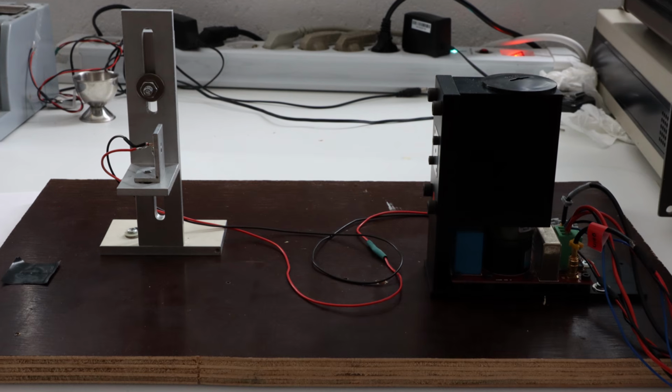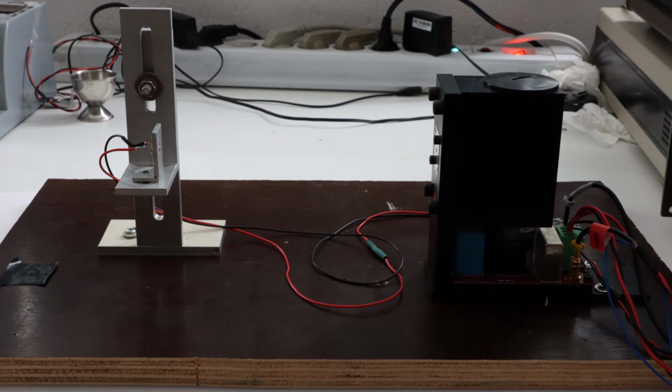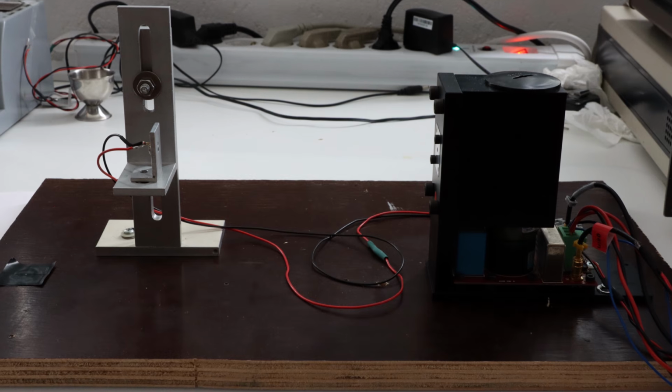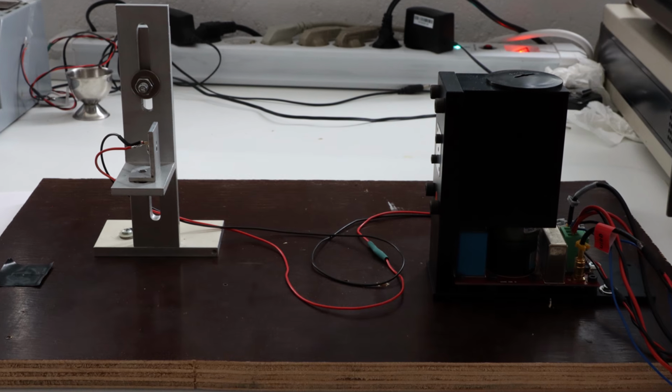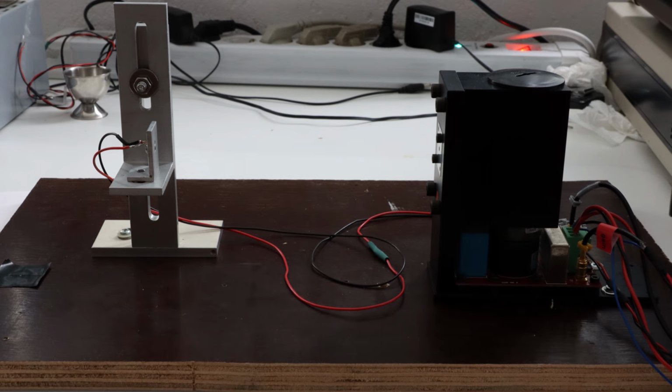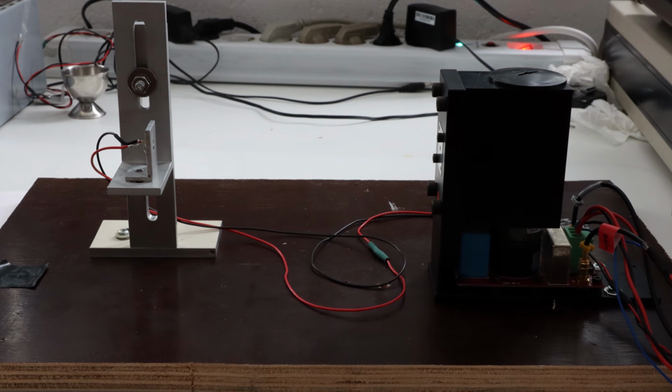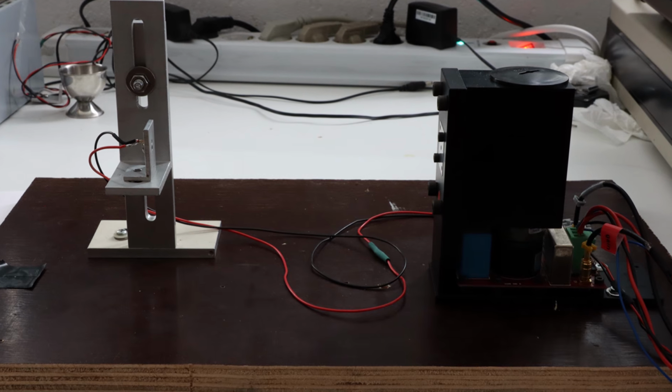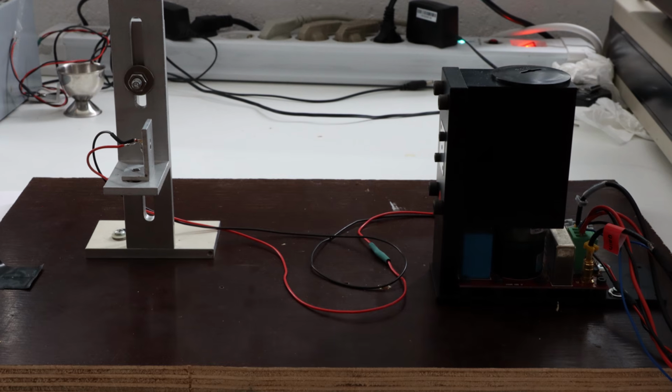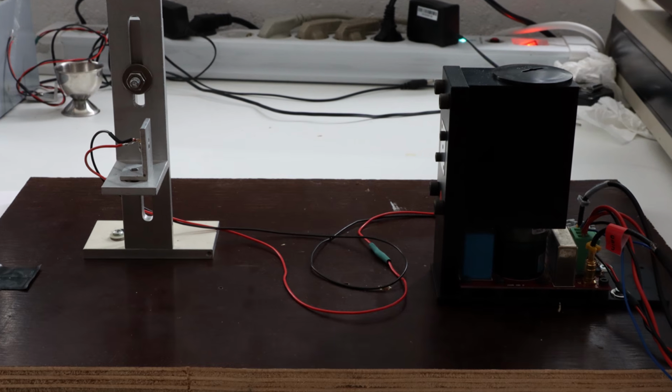Since a photomultiplier is really incredibly sensitive to light, normal indoor light levels will completely overwhelm it, and in fact you should never apply a high voltage on a photomultiplier under regular lighting conditions, because if you do, you can easily damage it. So you need to perform any experiments in extreme darkness, and this turned out to be quite a bit harder than I expected.